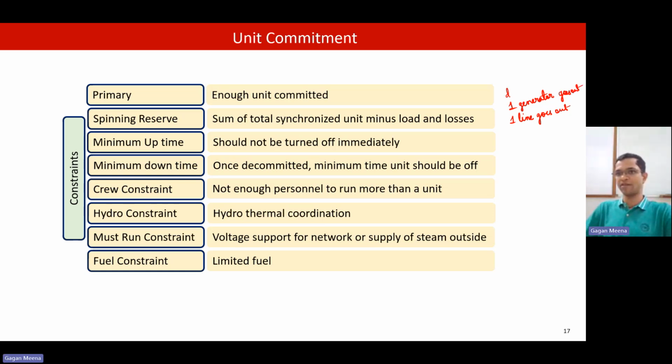or demand increases, we should still be able to meet the demand. And that is possible by spinning reserve. They are committed, but they are not generating.